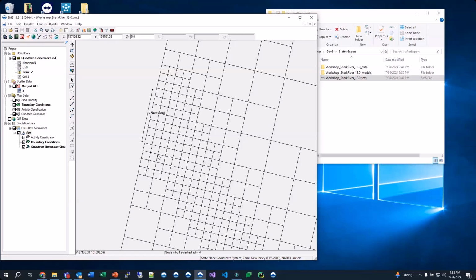Yes. When I apply the river boundary, we often see this kind of issue. If the boundary sits on a land cell, it will cause model instability. Usually the user has to manually open up some cells to have water there, and then you allow some water flow in, and then the model gets stable.